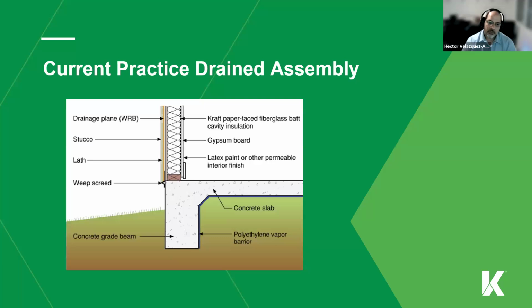So leave the weep screeds alone. Don't seal them. Let them be free so water can come out of them. And that will keep your building safer and give it longevity. If you seal them up, yeah, go ahead, Nick.